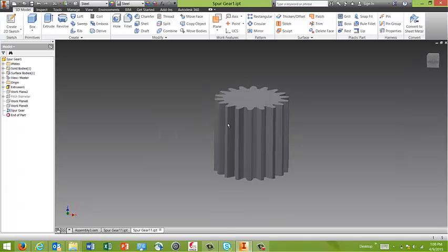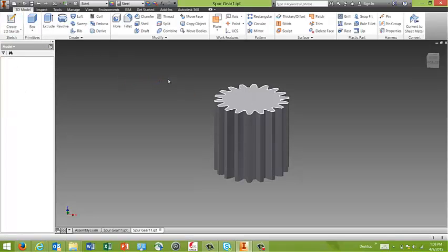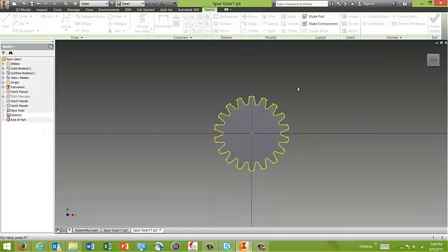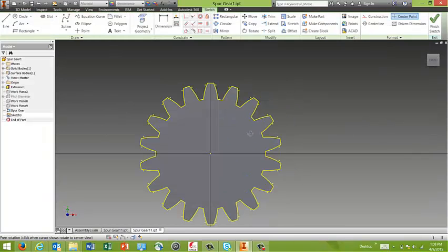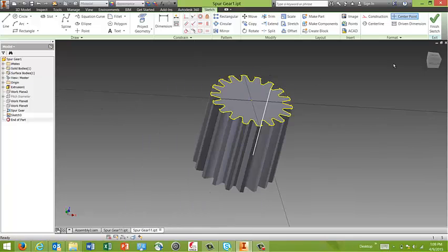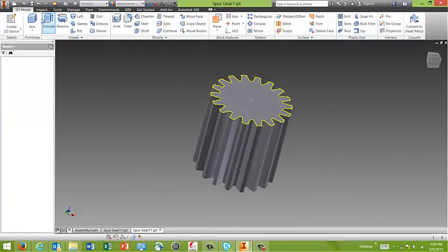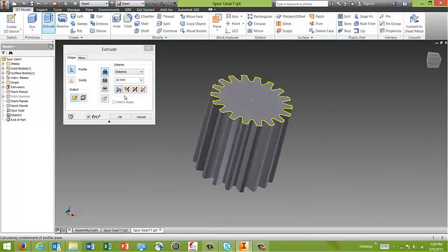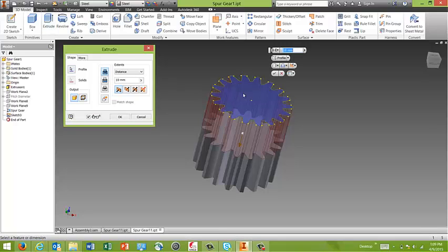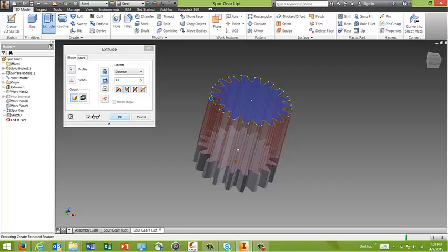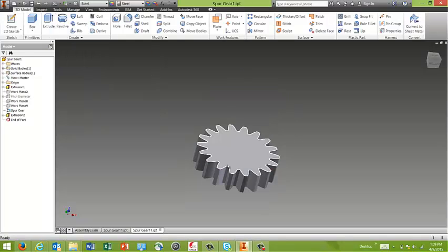Okay, if you find that the gear width is too high, you can actually reduce the gear width by, I can finish sketch, and what I can do is I can extrude it. I can extrude cut by 10 millimeters or maybe even more, 15. I feel that it's too much, right? And I click OK. And what it does is that it cuts the gear teeth.